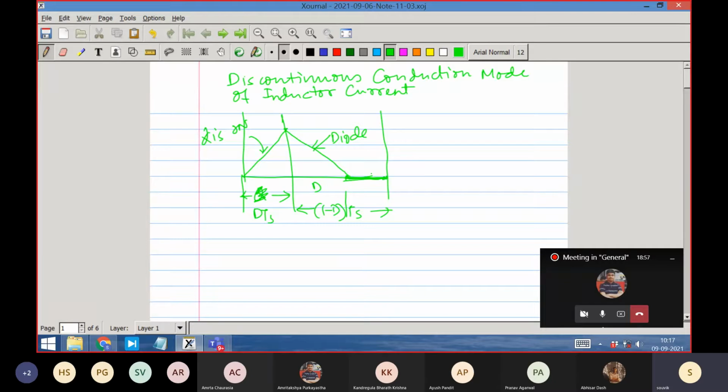That doesn't mean the output voltage is 0. Current in the inductor reaching 0 doesn't mean that. It means that the capacitor is simply supporting the load without being helped by the inductor. That is what it means, right? So you see a third state coming in. We have 3 equivalent circuits now.